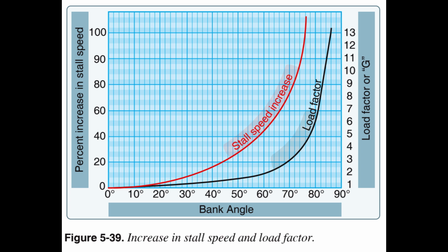The AOA must increase as the bank angle increases to counteract the increasing load caused by centrifugal force. If at any time during a turn the AOA becomes excessive, the aircraft stalls. At this point, the action of the aircraft during a stall should be examined. To balance the aircraft aerodynamically, the CL is normally located aft of the CG. Although this makes the aircraft inherently nose-heavy, downwash on the horizontal stabilizer counteracts this condition.